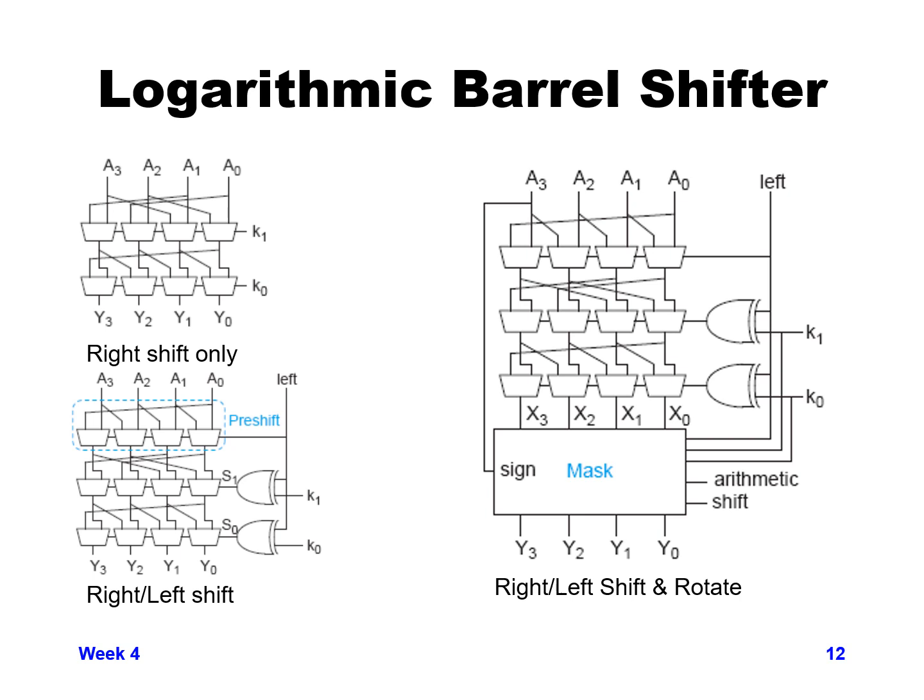So if you remember, I said if we want to shift left, we can do that by shifting right by inverting K and then shifting 1 plus the inverse of K to the right. So here what we do is we have a value. If we're doing a left shift, we first do a pre-shift of 1. So the top row there is, if left is coming in, it has a value of 1, we pre-shift 1 to the right.